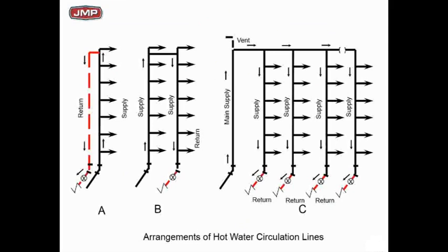And we talked about typical risers coming back and forth, up and down. Basically, you want a check valve coming out of each one. Where your red return line is coming, we want to make sure on the return side you have a check valve. So if your pressures get out of whack, you don't get reverse flow through the return line.